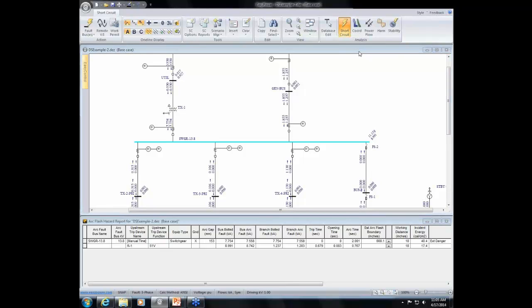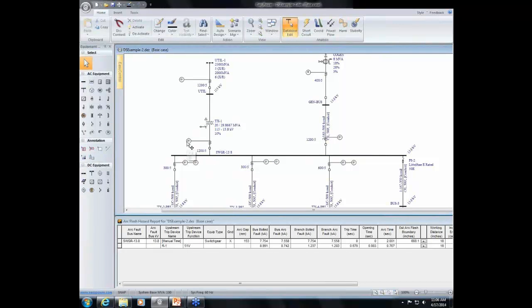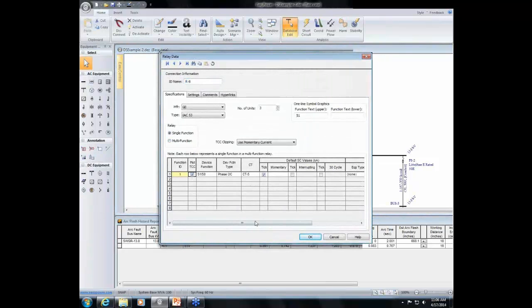There are cases where, depending on where you're working on this gear, you may be able to include both of these mains. Maybe you can only include one. But the intention, going back to the example that I was trying to show, was that I wanted these devices to be the ones that were tripping. Basically, in stability, I'm going to say no to that. So what I did was I just unchecked the plot TCC checkbox. So in stability, it bypassed it.